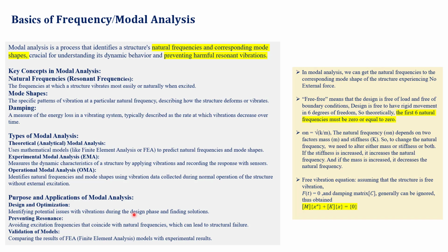What we could do is increase the width and height of the fastener. By that we add material, and in short we increase the stiffness, and then the frequency increases, so we can avoid the resonance.